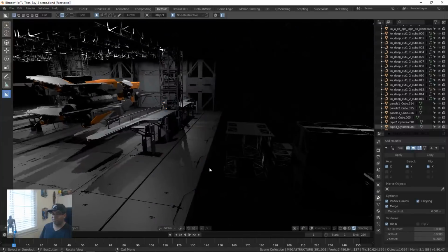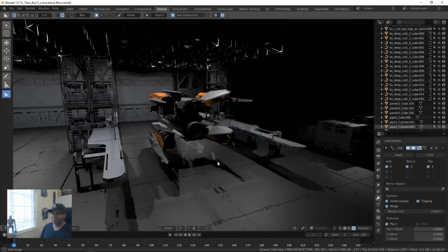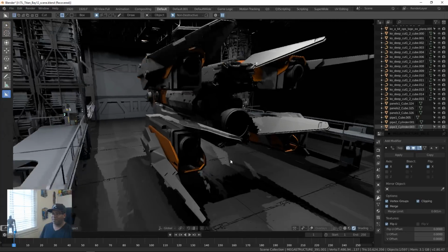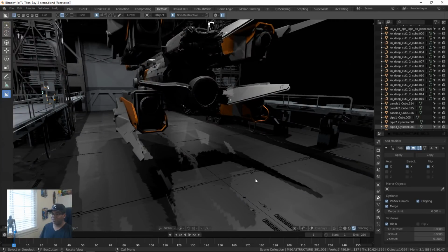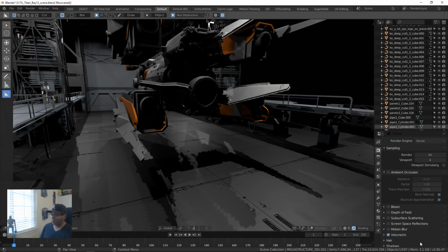The only thing is, while we're operating in speed, a lot of the effects like bloom and some of the shadow richness and depth are going to look a little bit choppier because it's kicking it down to its lowest resolution, right? So in properties, you can go and change the render quality a little bit. If you have ambient occlusion, you can change the distance and whatnot.